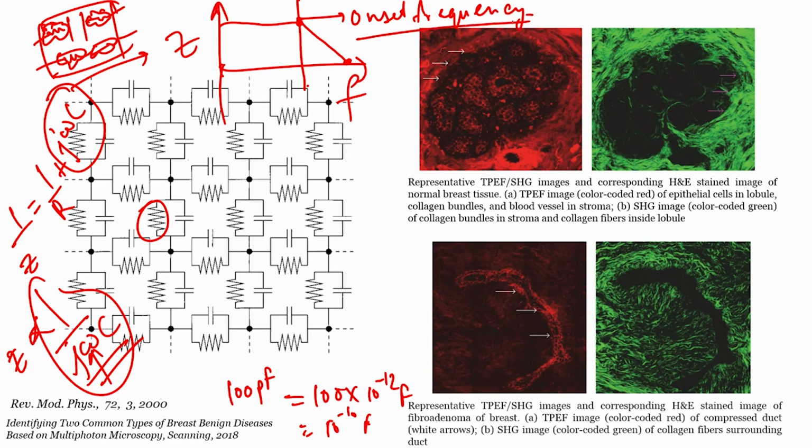Why is it called onset frequency? It is called onset frequency because this is the frequency at which AC conduction or frequency dependent transport dominates the DC transport, and since it is the onset of AC conduction, it is called onset frequency.